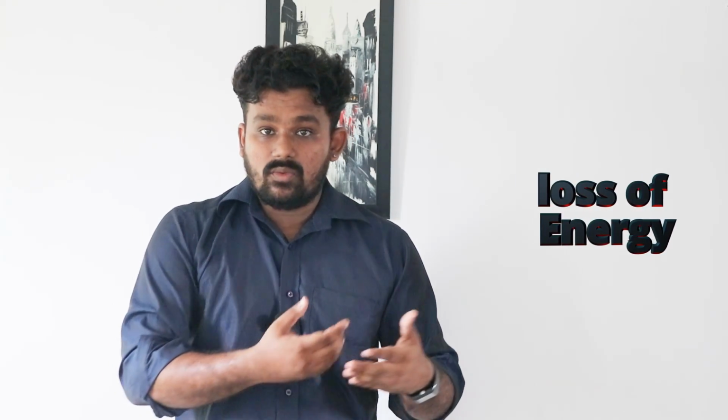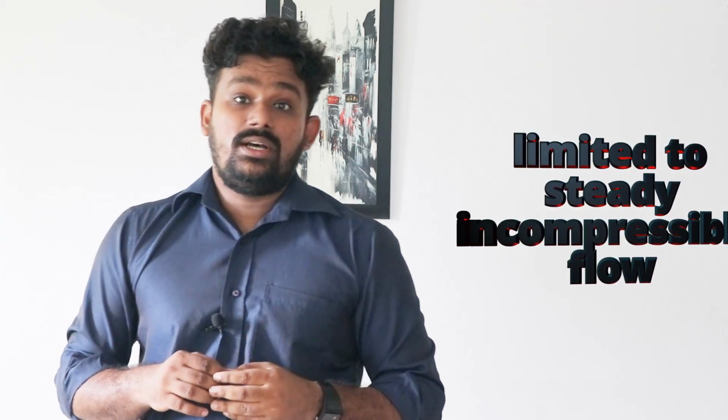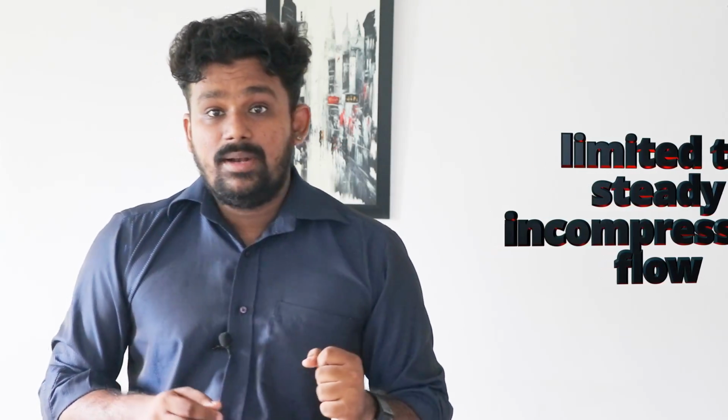Third, no loss of energy is considered. When a fluid is flowing there is loss of energy, but this energy loss is not considered. Fourth, it is only applicable for steady and incompressible fluids. So these are some of the limitations of Bernoulli's equation.